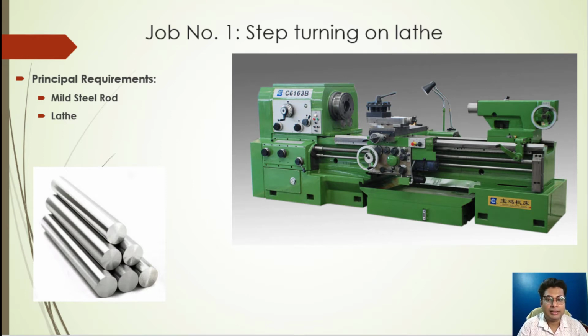Mild steel is a type of low carbon steel. Now, carbon steels are metals that contain a small percentage of carbon, which enhances the property of pure iron. The carbon content varies depending on the requirement of the steel. Mild steel contains carbon in the range of 0.05 to 0.25%, making it malleable and ductile.